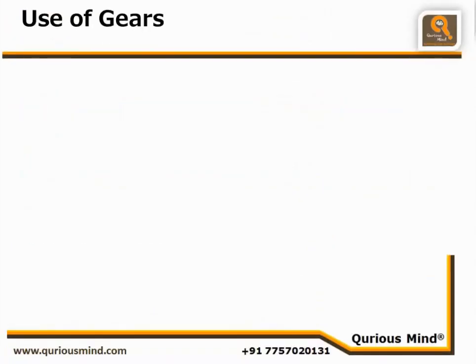In addition to this, gear can also be used for a few other purposes. Let's understand each of these in detail. Pay your highest attention as this is going to be required every time you think of making a new robot. Let's do a small experiment. Take two gears from your kit, one big and the other one smaller. Mesh them and rotate the big gear using a shaft. Count the number of rotations of the smaller gear when the big gear is rotated once.